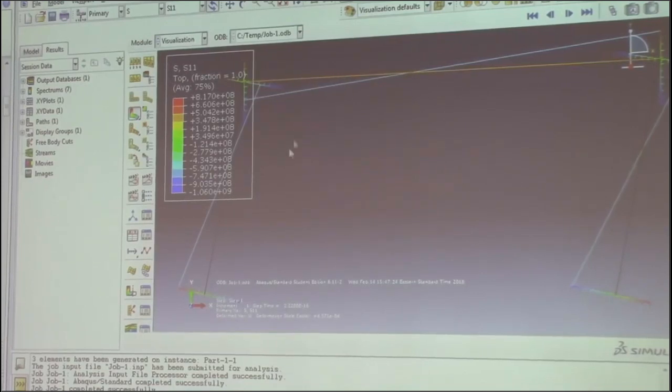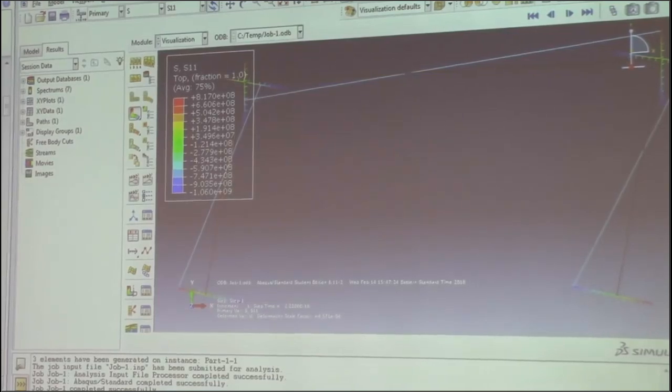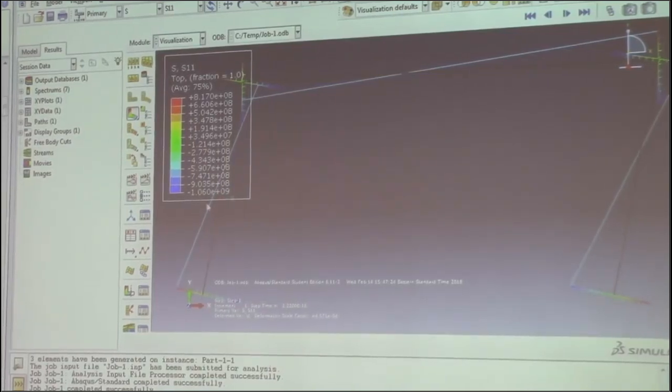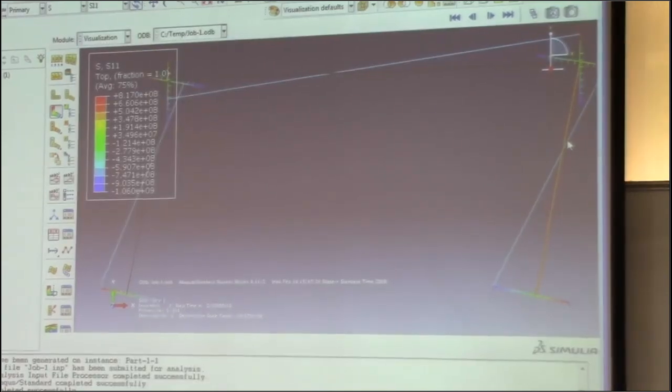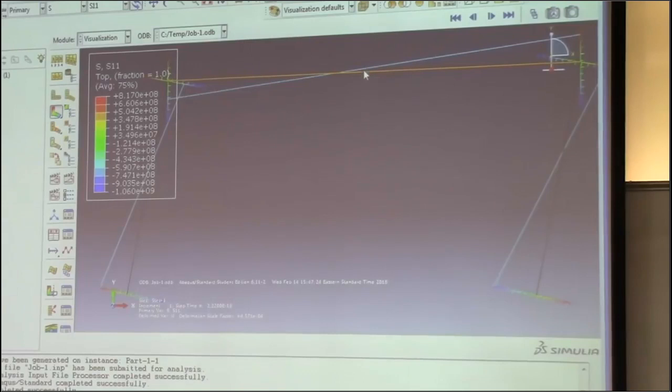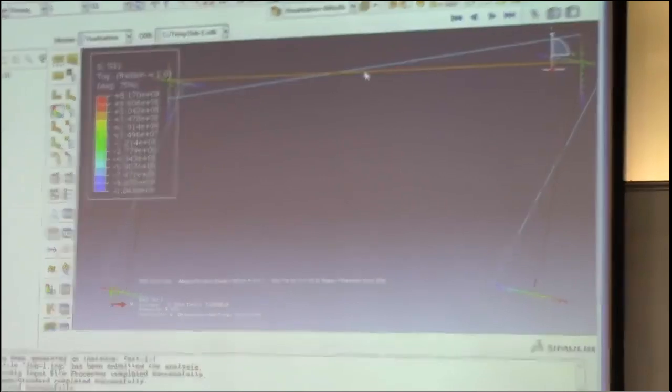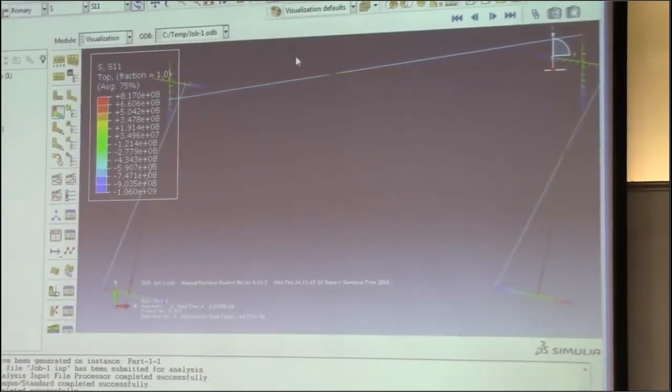Yeah. So if I change the mesh to one element here, one element here, one element here, actually these two are the same, right? Because these two beams are only subject to concentrated force. And for concentrated force, the beam element type in ABAQUS can give you an accurate result. So one element is good enough. But for this beam, because it has concentrated force and distributed force at the same time, and ABAQUS can only do the approximation, if you use just one element, the result is not accurate.